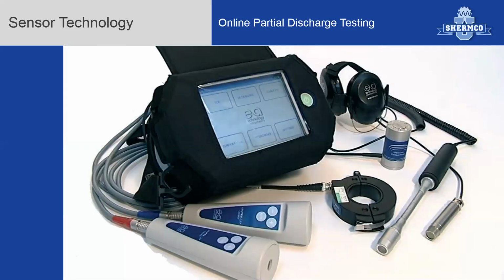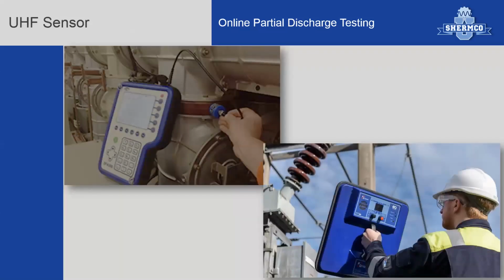Here I show a little bit more proper example. Here we show a piece of test and measurement equipment. This would be the partial discharge receiver, and we see various antennas, if you will, or sensors. Each of these sensors operates at various bandwidths. Let's start with the UHF sensor, or the ultra high frequency sensor. Ultra high frequency or UHF sensors, depending upon the manufacturer, will typically operate in a bandwidth of 300 megahertz out to about 1500 megahertz. Again, from manufacturer to manufacturer, there might be some slight variation to that overall bandwidth, but somewhere in the realm of radio frequencies and microwave frequency ranges.